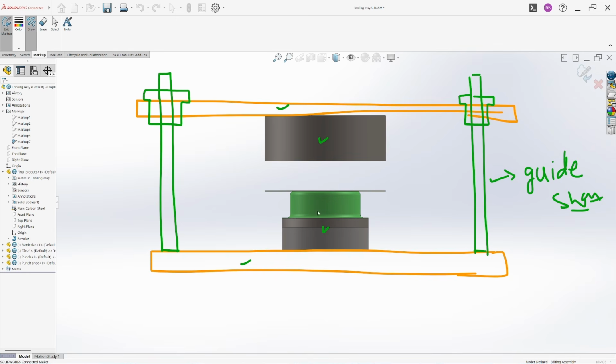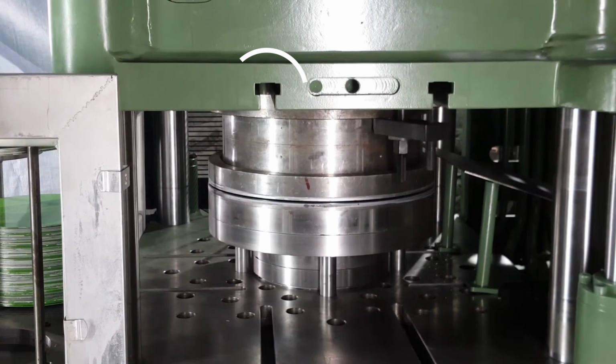Let's say we fix our punch and this punch spacer with the base plate with a doweling, of course, or a step guiding. And we make our die adjustable in the X and Y direction, which we can achieve with slotted mounting. So whatever misalignment there is, we will be able to align the die with the punch. Or we can use this kind of T-slotted plates with the clamp, something like this.